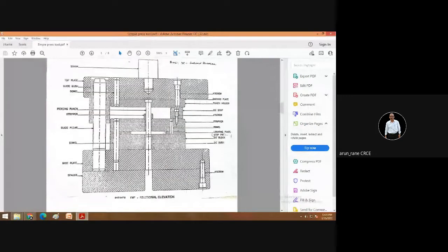Then there is one more, that is how to hold this component. Now this and this are held together by this screw. See, remember, look at how it is shown. There is a threading here, no threading here. So this will have a free hole, and this counterbore will also have a free hole. Again, this and this are joined with the help of this screw. Now this is a die stop.